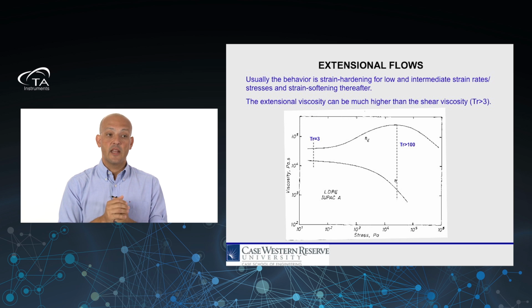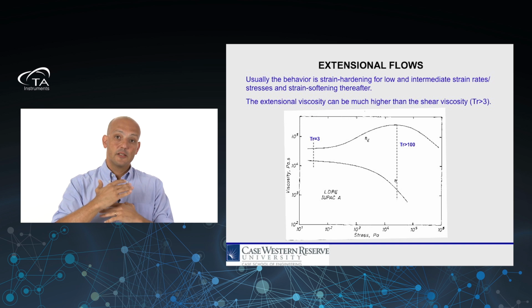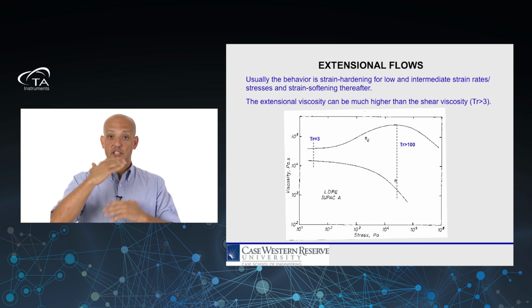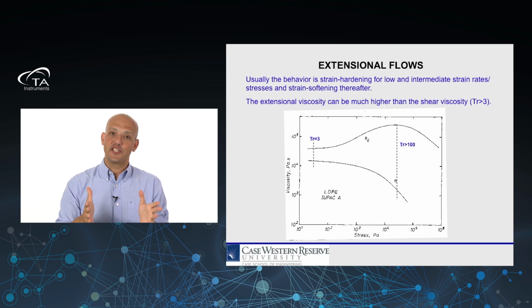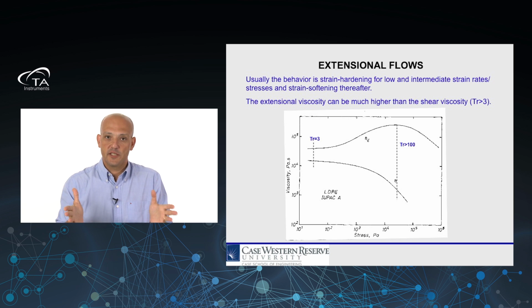Okay? And as luck would have it, this discrepancy between the shear and the extensional viscosity is highest in the typical processing range of polymer processes.